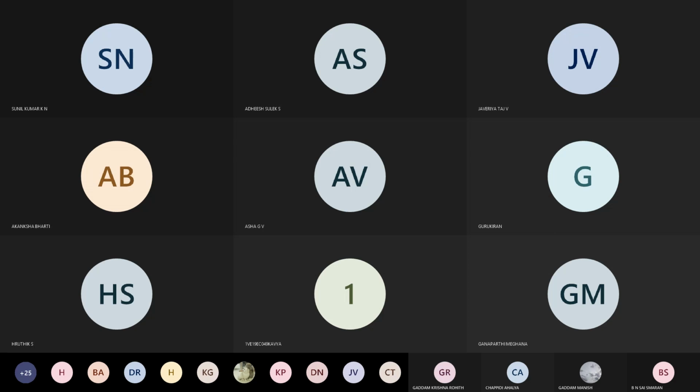So R is the same. RA is equal to RB is equal to RC is equal to R, so it is equal to 3 kilo ohm. So 1K divided by 3K into the sum of the input voltage, VA plus VB plus VC, 1 plus 2 plus 3, and you will be getting the output voltage. It is summing, it is nothing but an averaging circuit. It will be equal to minus 2.